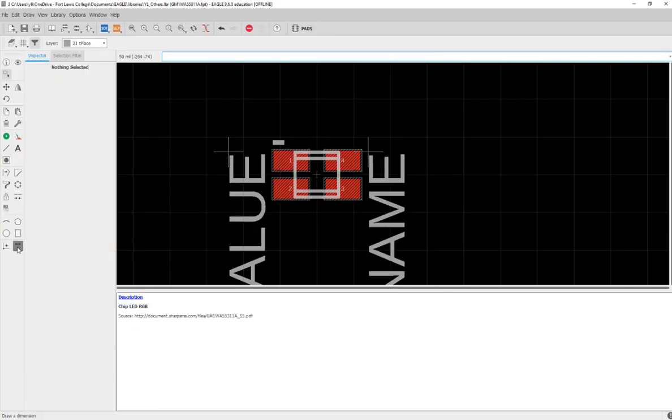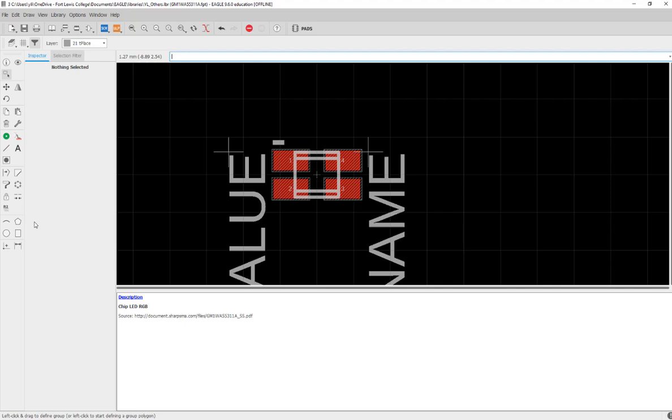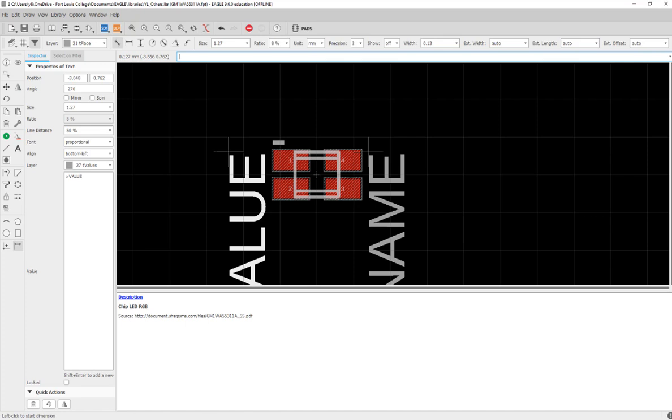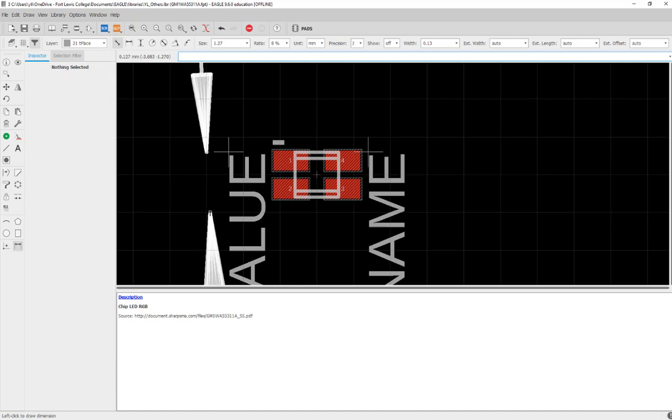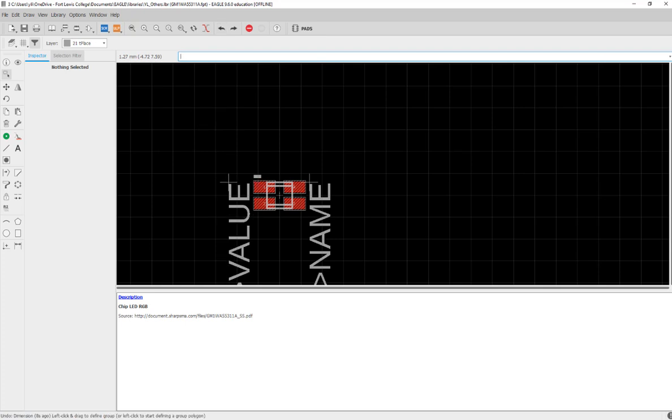And if I measure it, make sure you change the grid unit to millimeters, so it's measuring in millimeters. So this dimension has to be 2.2 millimeters. Press Alt on the keyboard so you can define a finer grid. Right click. Let's see. This is only 2 millimeters. It's definitely not enough. So I have to change the dimension a little bit.